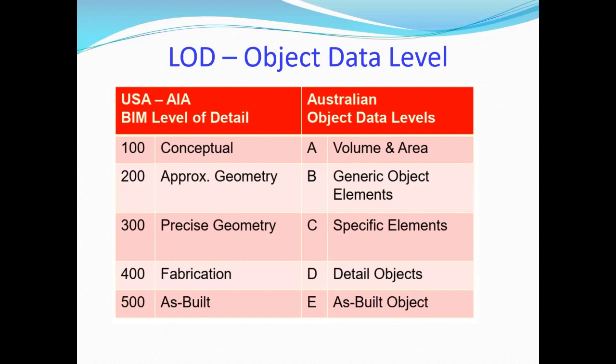In the 200 series, we put in the sizes, but there's no rebar or anything, just the sizes. In the 300 series, we normally include the sizes and the rebar sizes and so on. So it's like documentation modeling. Then the 400 series is fabrication. I can include the rebar sizes, but to fabricate, you're familiar with the bar bending schedule, right? At fabrication time, you have to produce that, and that information is supposed to be contained in the model.